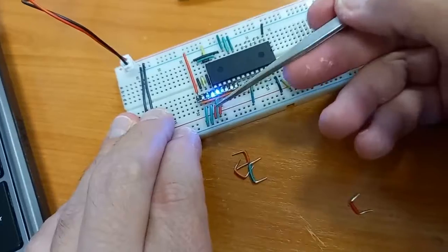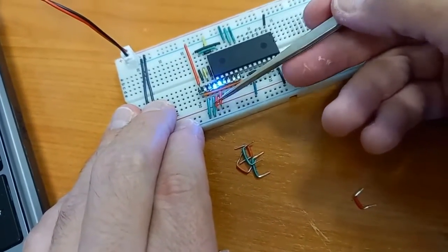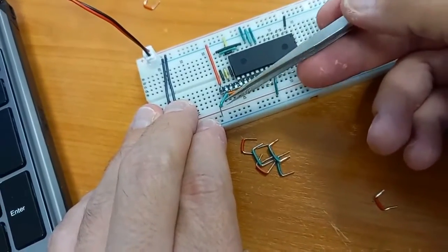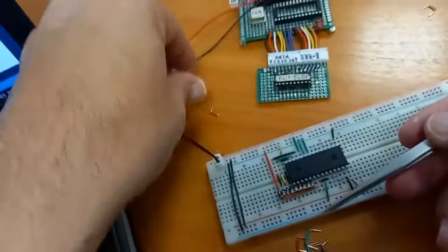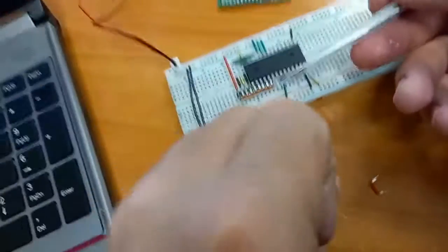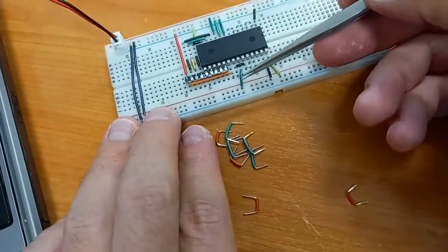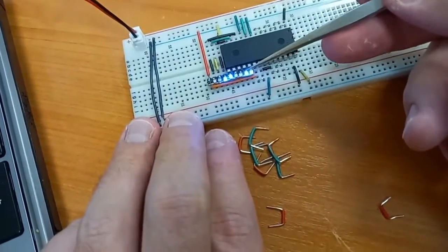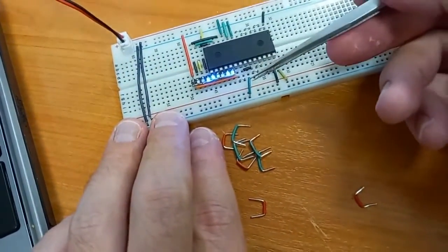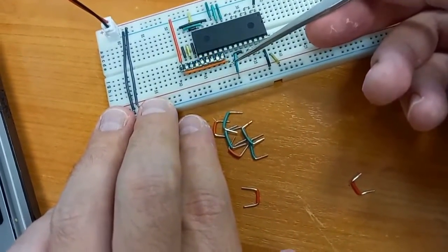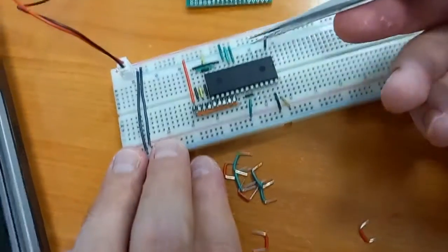Now we will remove the number from here, and we will check if we have written this number correctly. For checking, we will enable the output, take the output and put it to enable. 11001100. That's correct. Address number 1 has been written.